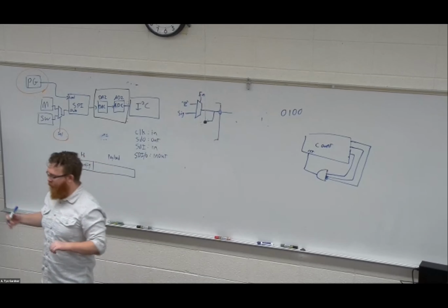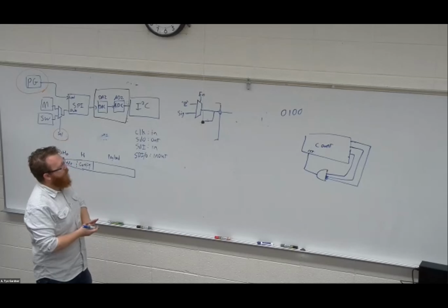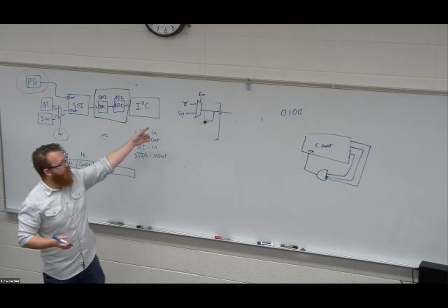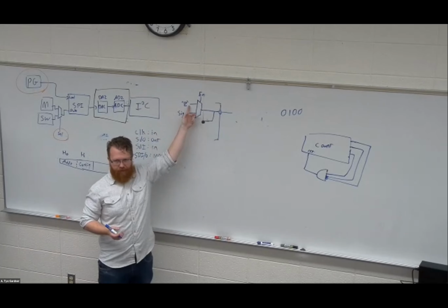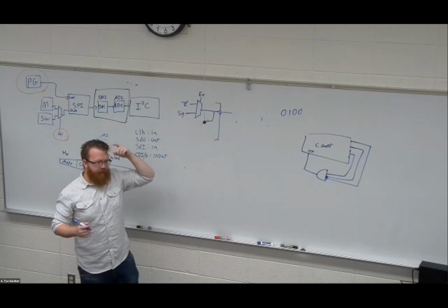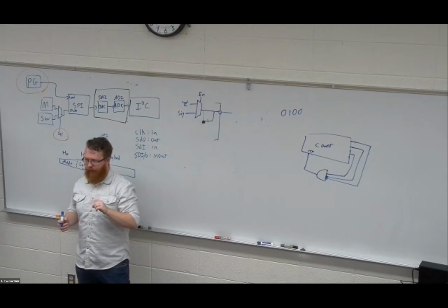It's still an output enabled buffer. It just turns out the output enabled buffer is a little bit tricky to write in VHDL, and writing it as a mux, where if I'm not enabled 0, just put a high Z. Ta-da.